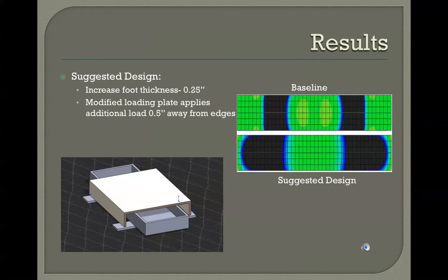However, before implementation of this improved design, the aircraft skin where it's being attached should be taken into consideration. This new maximum stress may be over the yield stress of the skin material. These results are significant because they can be broadly applied. They accurately show the stress distribution on the adhesive loaded through similar instruments. Later tests can be tailored specifically to surfaces it will be attached to, so material yield tests can be conducted. Additionally, further analysis should be conducted on fillets with solid elements to verify the poor results obtained in this report.